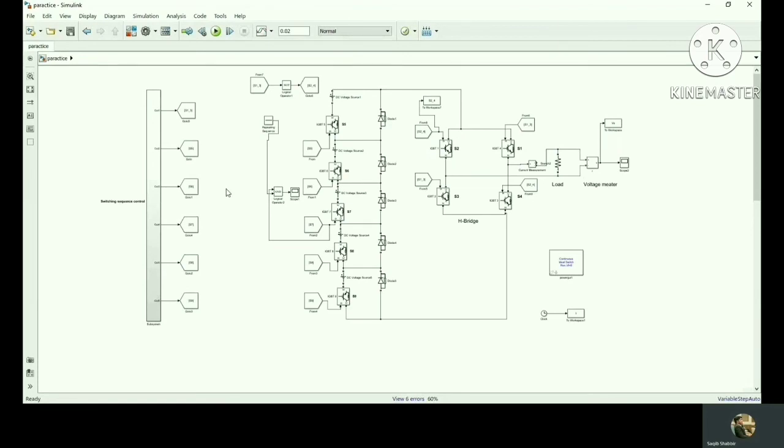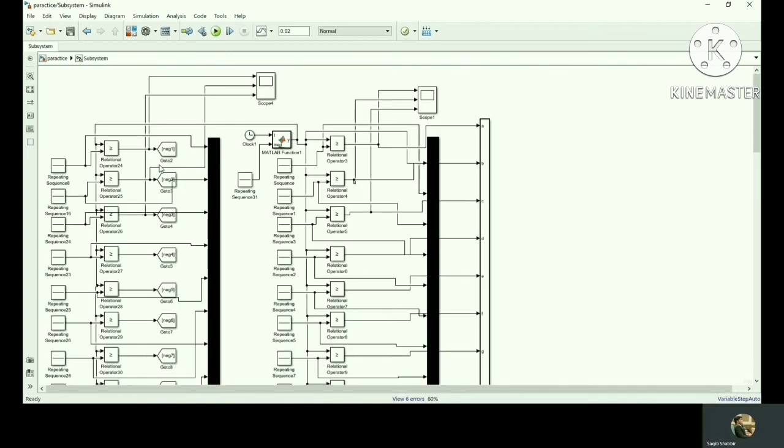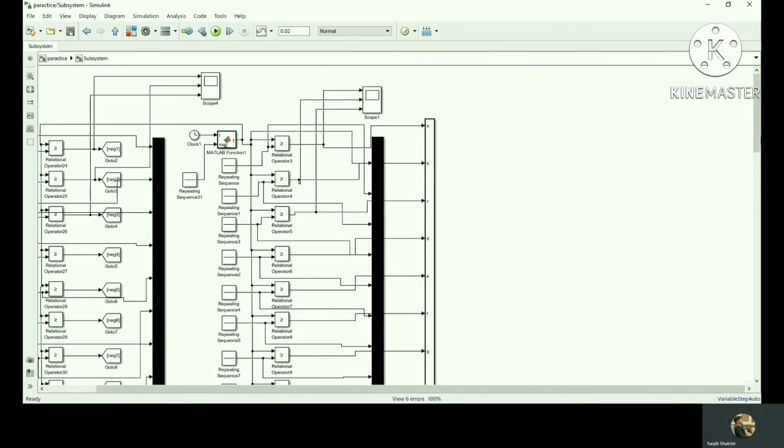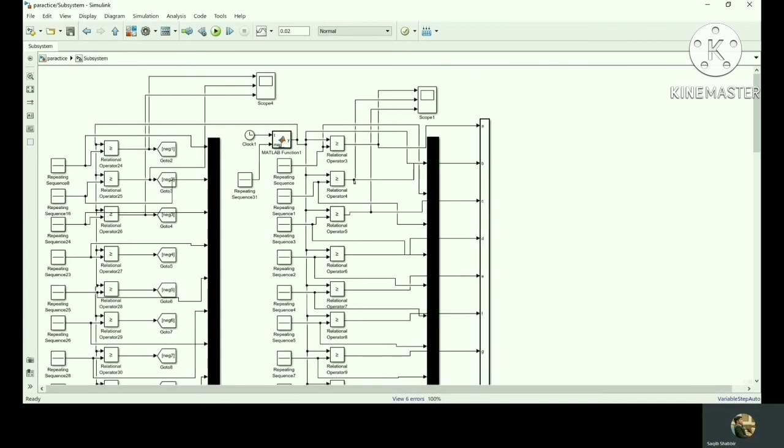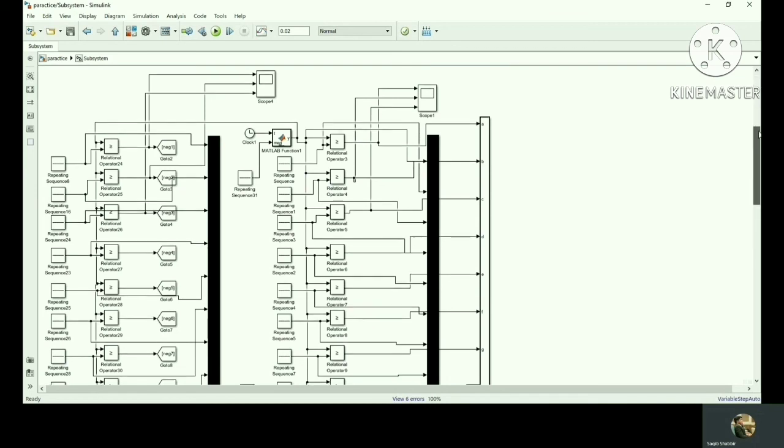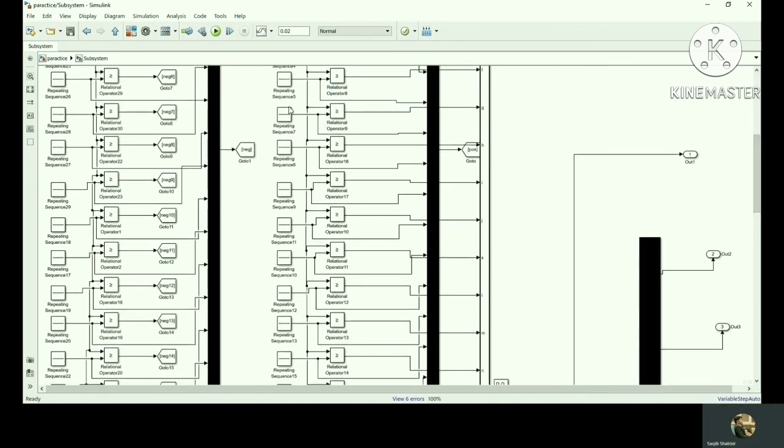We designed this project on MATLAB Simulink, and this is the brain of the switches. All this work is implemented through code on Arduino, using a microcontroller. We use different switching levels. This is not a big deal, it's very simple using coding. And these 5 switches are used to trigger the 4 H-bridge MOSFETs to convert DC into AC. This is a very economical and efficient design of a multi-level inverter with low THD.